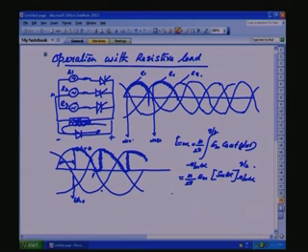So, the final equation in terms of the RMS value, root 2 E, where E is the RMS value, m by 2 pi into 1 minus sin of alpha minus pi by m. This is the general equation.